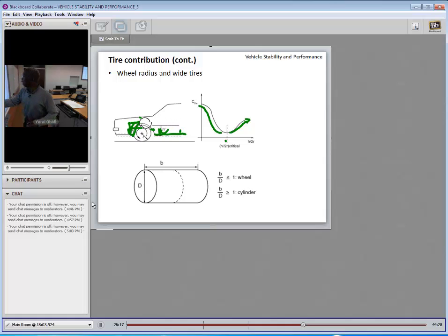And so the larger this becomes beyond the critical value, the greater the body that's exposed to drag, and greater is the drag on the vehicle. So H over 2R, for a given vehicle, there's no fixed value for H over 2R. It depends on the vehicle you have and the dimensions. Aerodynamic testing has to be done. Real vehicle testing has to be done for each car design to determine the critical H over 2R. And beyond that value, the drag coefficient due to the wheel will increase.